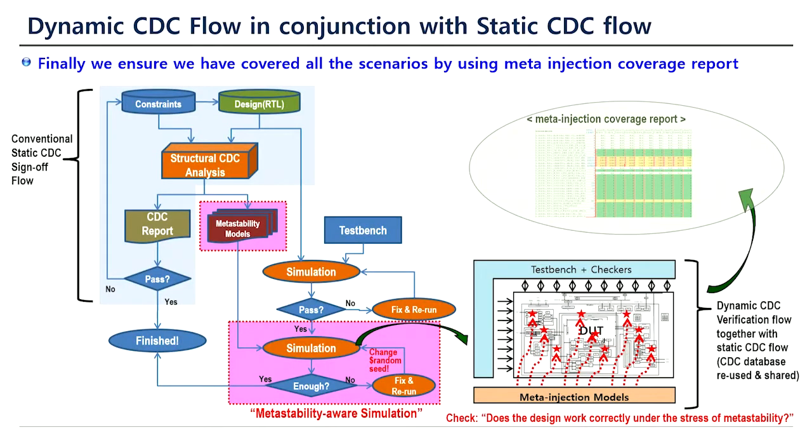That is the key idea. To model this kind of situation, we use the traditional static CDC analysis. With the help of the CDC tool, we can extract much information about synchronizers and fan-in cone logic.